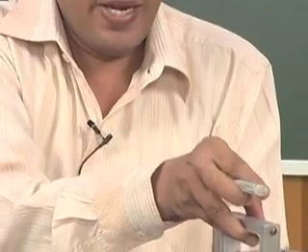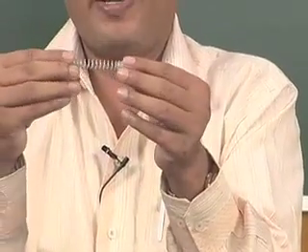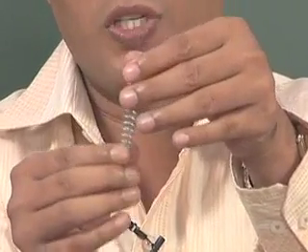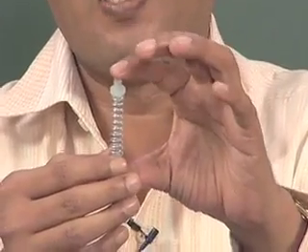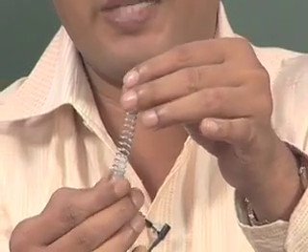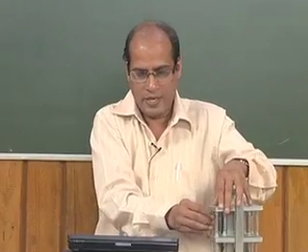So, this spring can be a linear spring or it can be a nonlinear spring. So, if in the force displacement diagram the force is proportional to the displacement, then in that case it will be linear, otherwise if it is not satisfying that, then it will be a nonlinear spring. So, in case of using this nonlinear spring, you can write the equation of motion in this form, but for this 2 degree of freedom system you can write 2 independent equations, or you can have coupled equations also.